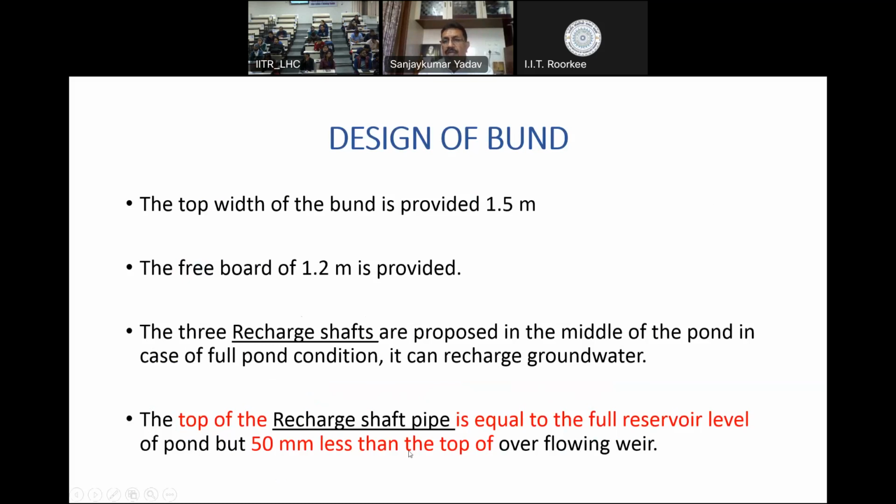This is another issue in India. Over a period of time, whenever the tank overflows, there may be a small stream which will be carrying water to the nearby water body or nearby river. And you will find that all around the pond, there is encroachment or unpaved areas. So in monsoon season, when the pond becomes full or it overflows, the adjoining areas get flooded.